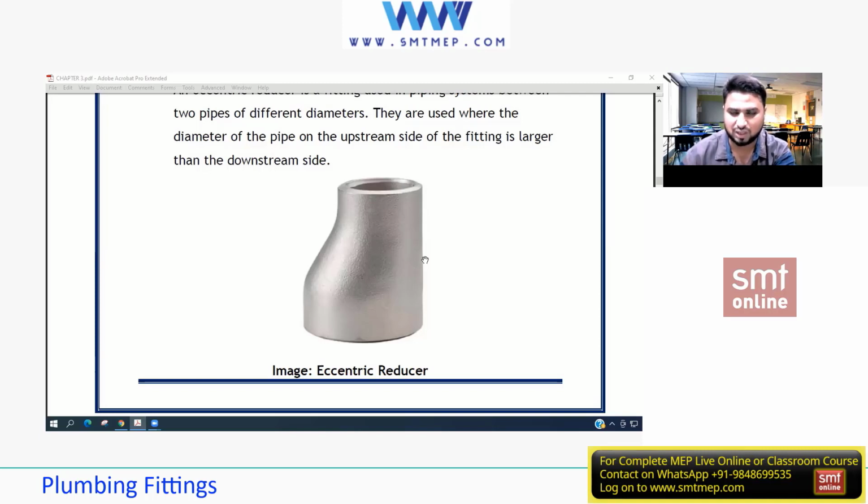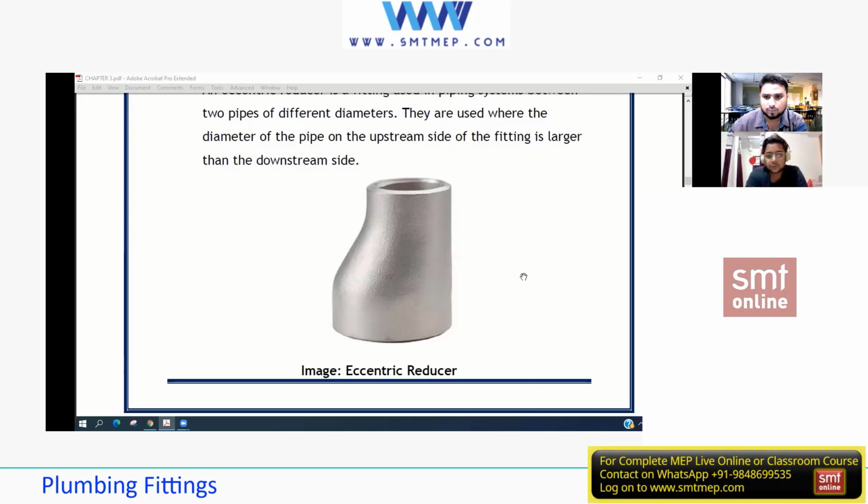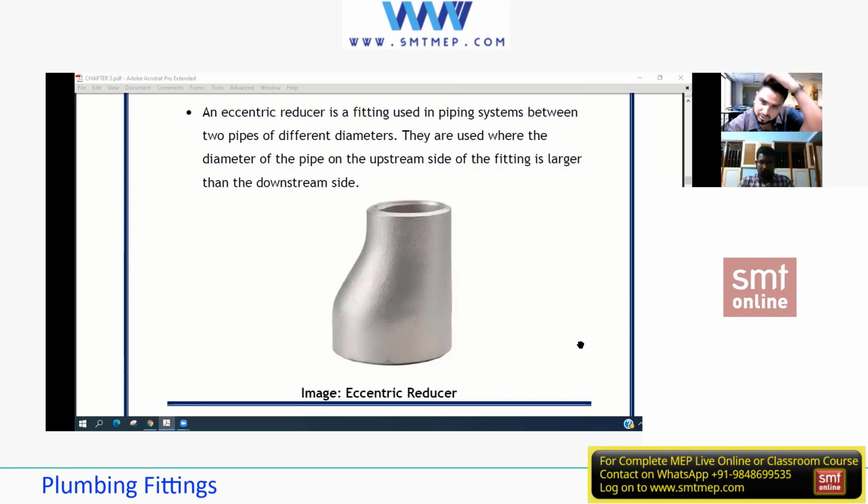What are air gaps? Inshallah, we'll be coming back to you, Fahad. Okay. Okay, sir. Next is what? Sir, about the cavitation. Yes, please. Sir, in all kinds of pump, we use a eccentric reducer at the suction side. Suction side. Yes. All kinds of fire pumps and chiller pumps and other pumps, where there's a shift in diameter, we'll be using this, whatever the pump is.